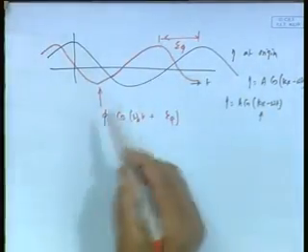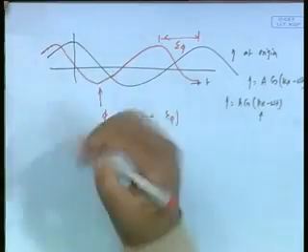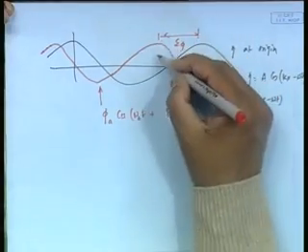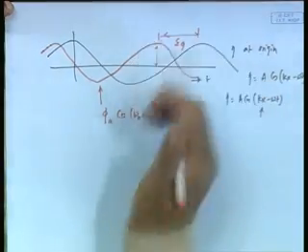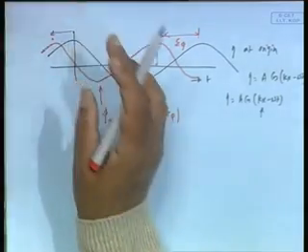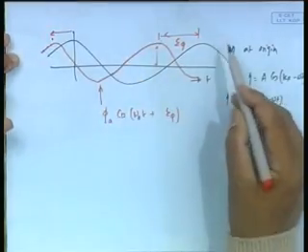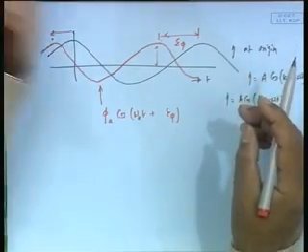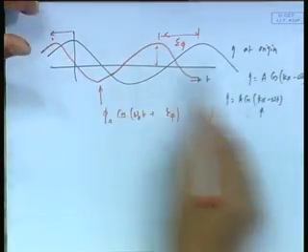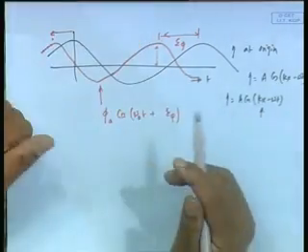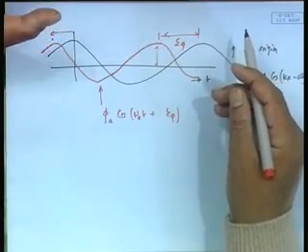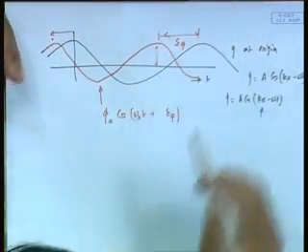So, you see, the point is that I would know my time history, all the points on this, if I only know two things, that is the amplitude and its location. In fact, this E phi sets where the origin, the starting point of the signal, is. This E phi fixes the position of the signal on the t axis in principle. On the t axis, it tells me from where it starts, that is my phase, and the amplitude tells me the maximum.